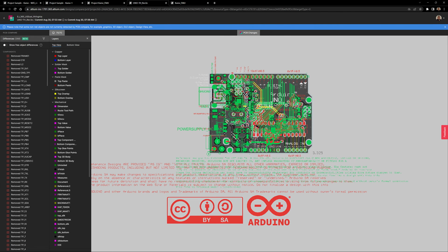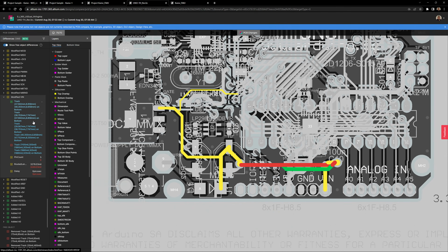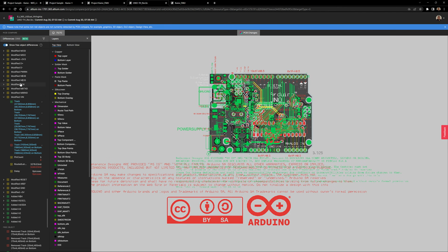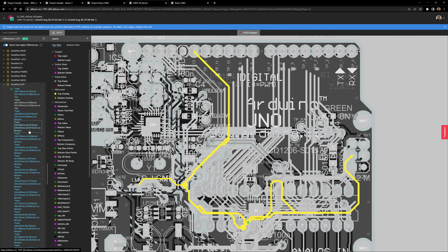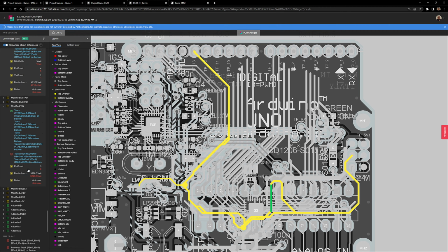Okay, so moving on to the PCB compare, we have the differences pane on the left-hand side. Here you are able to see, as I mentioned, red for removed, yellow for modified. If you click on the individual items, you will navigate through the design itself. And you can see the color coded to give you that simple visibility overall into the design. Notice that each individual section of a trace, for example, has that information brought in.